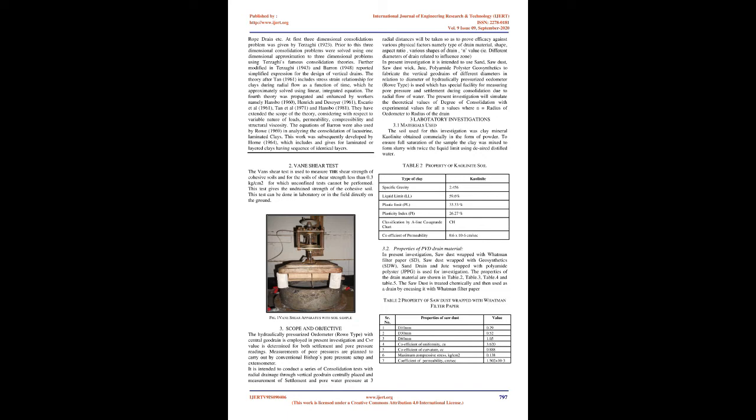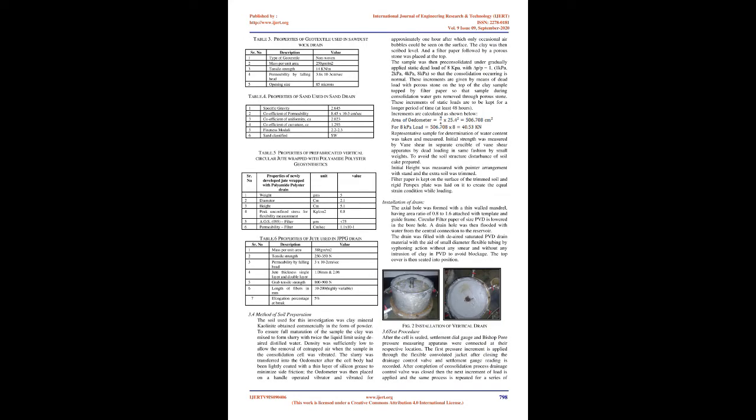At first, the three-dimensional consolidation problem was given by Terzaghi, 1923. Prior to this, three-dimensional consolidation problems were solved using one-dimensional approximations with Terzaghi's famous consolidation theories. Further modified in Terzaghi, 1943, and Barron, 1948, reported a simplified expression for the design of vertical drains. The theory after Tan, 1961, includes the stress-strain relationship for clays during radial flow as a function of time, which he approximately solved using a linear integrated equation.